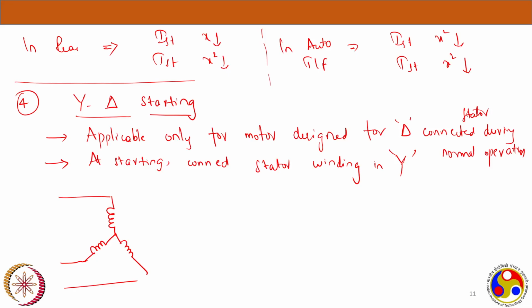Now I starting in the line for star delta is equal to I starting winding in the star delta. Now what is this again? Here you are applying the phase voltage. Can you tell me what is the phase voltage in a star connected system? Your line voltage and phase voltage will differ. Your phase voltage will be line voltage by root 3.